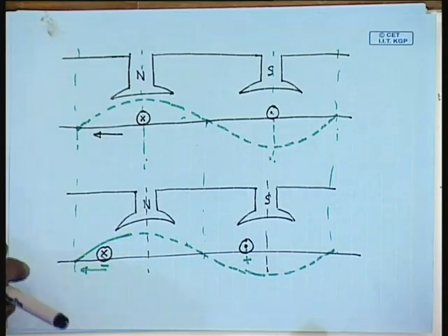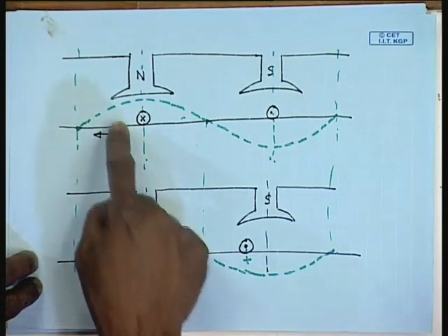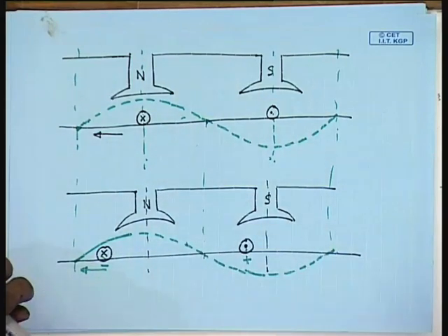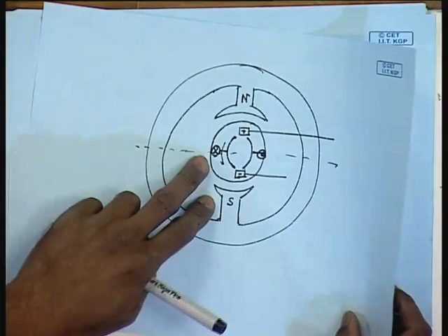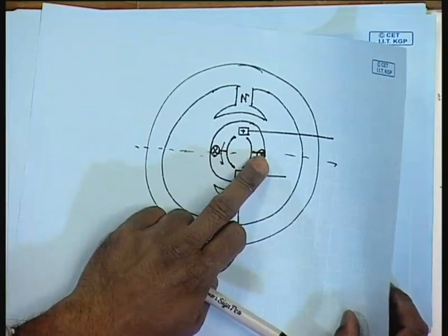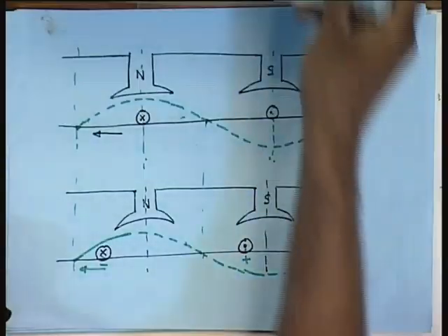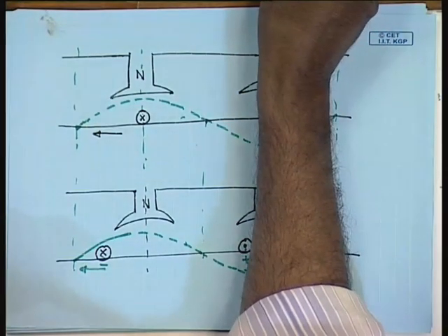Voltage will still be induced because there will be a rate of change of flux linkage. Now, as long as we are not connecting any resistance or any external circuit to the coil, there will be no current flowing, hence there will be no repulsive or attractive force, and there will be no mechanical work done.